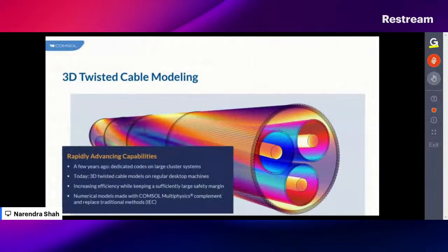The aspects that are supporting this, such as the advanced solver algorithms, sophisticated mesh configurations to build your finite element mesh, and even the sheer computational power, have improved the situation over the years. The biggest performance shift is caused by the introduction of a few computational electromagnetics features. These features could be in the form of twisted periodicity, or also short twisted periodicity. These are some of the features available to reduce your computational domain, because typically cables span hundreds and thousands of kilometers if it is a submarine cable. In those cases, we can't consider the entire domain of the cable.